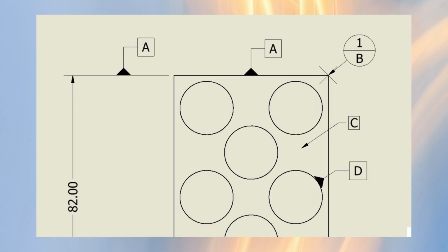This drawing shows us four different types of datum. Each has the purpose of specifying where measurements and dimensions should be derived from, but each differs slightly. A is perhaps most commonly used and specifies a plane for which the dimensions should be taken from. Note, on the drawing there are two A's. This is because the datum may be added directly to the plane, or to the measurement extension line of that plane. B is a target or point datum, and specifies an exact point to be used.